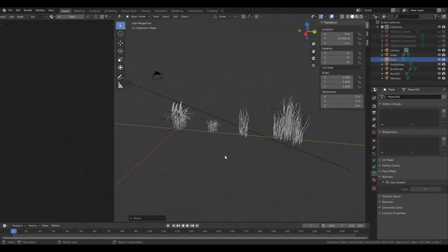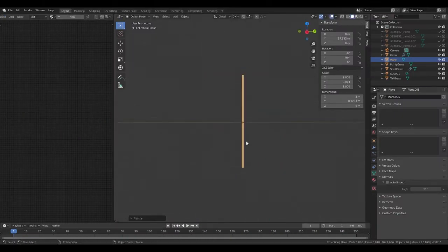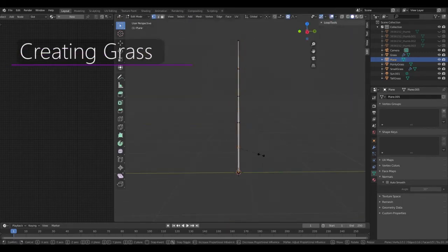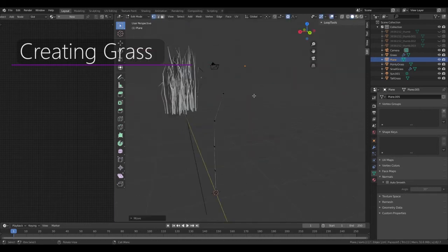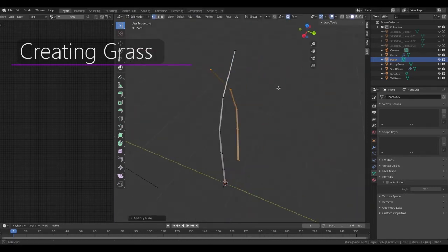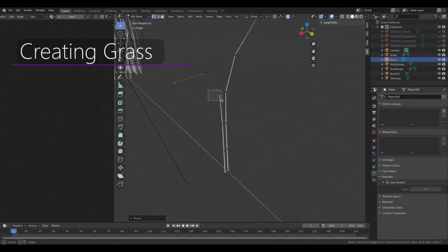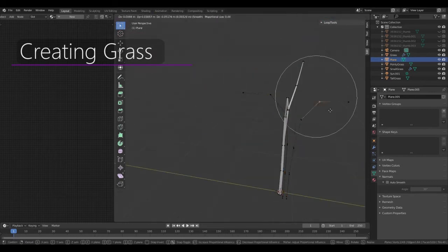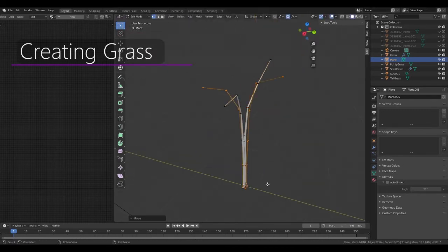Whilst the textures, references, and the high poly tree model were found externally, all other assets were created by me for the production. Modelling the grass was much more straightforward than the dinosaur. The individual blades consisted of plain meshes with a number of edge loops added and deformed to create natural bending. These objects were cloned to create different types of grass clumps, varying them on height, number of blades, and in which directions they pointed.